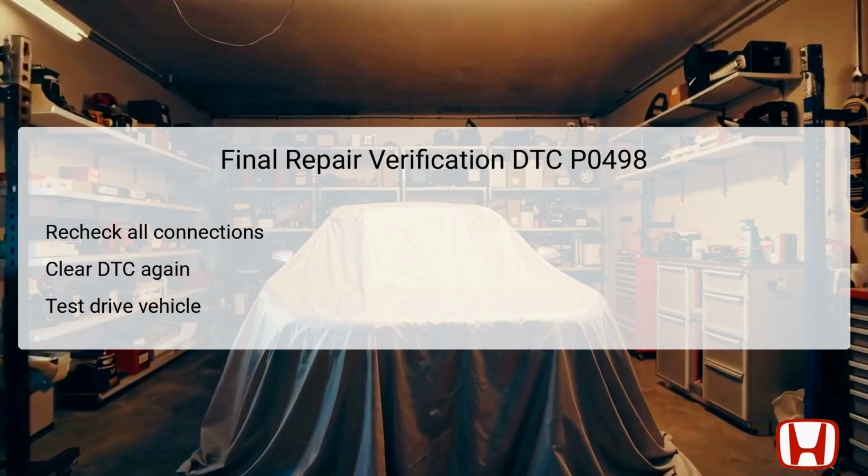After completing all identified troubleshooting steps, the final repair verification stage is crucial to ensure that the system operates successfully. Begin by rechecking all electrical connections related to the EVAP canister, vent shut valve, and the PCM, ensuring that no loose terminals or poor connections persist. Following this, clear the DTC once more using the Honda Diagnostic System, HDS, to reset the error code and prepare it for a fresh assessment.